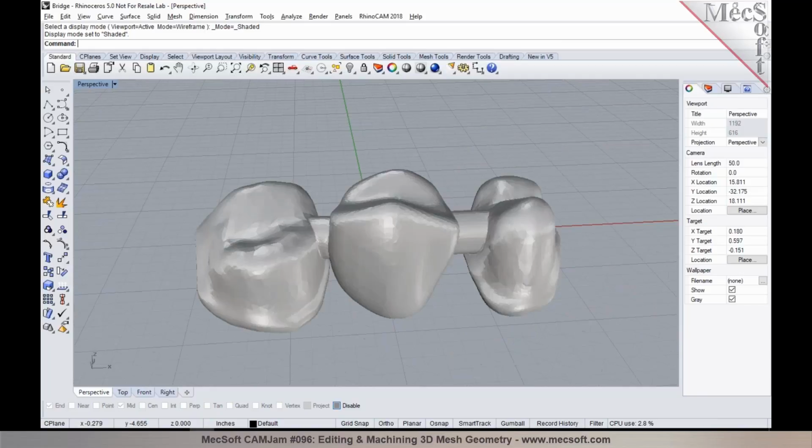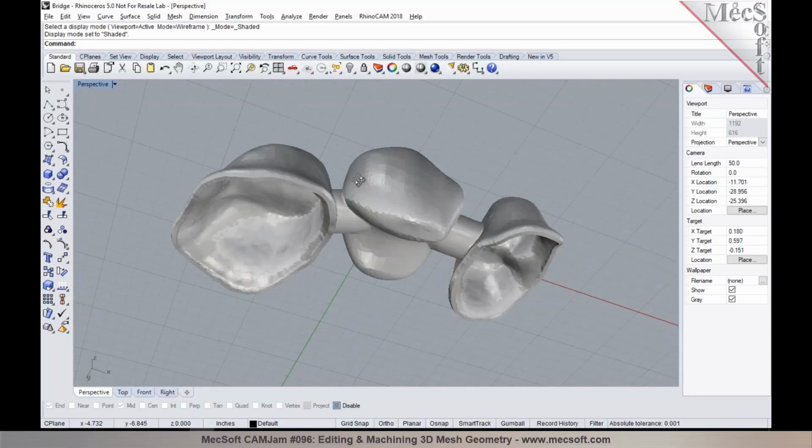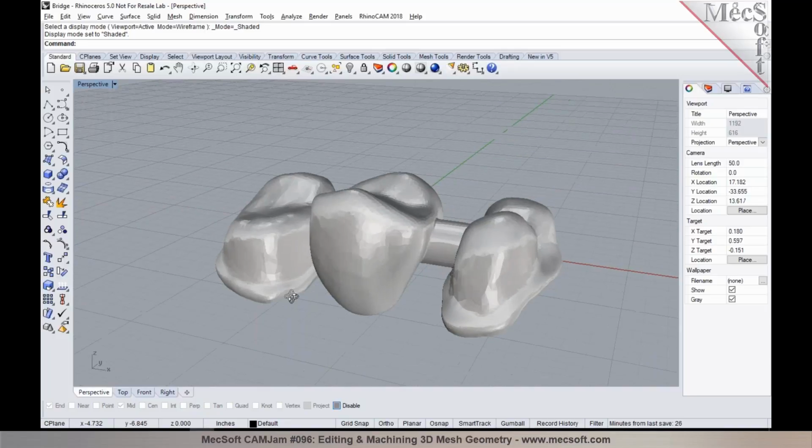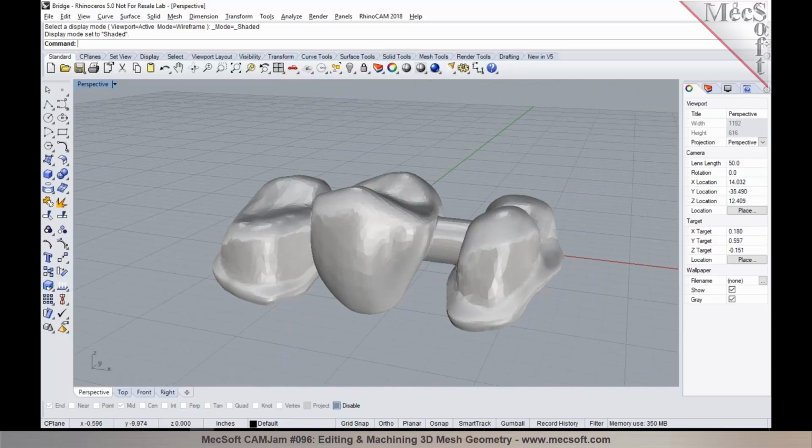In this case you have a bridge here, and you can be programming this from multiple different orientations on a rotary axis, 4-axis, or even if you have a 5-axis machine tool, you could use a combination of indexed and simultaneous 5-axis applications.